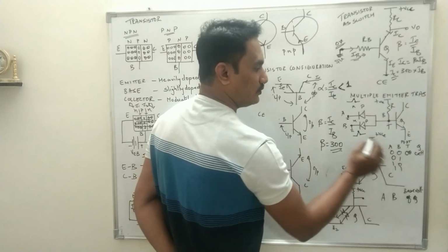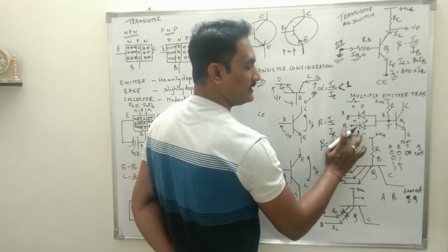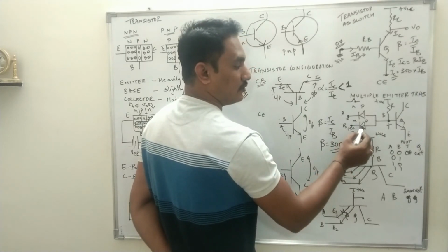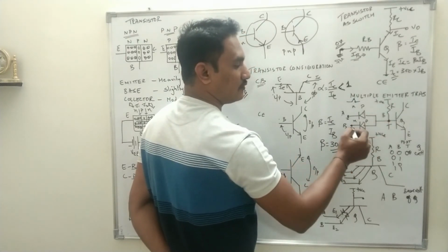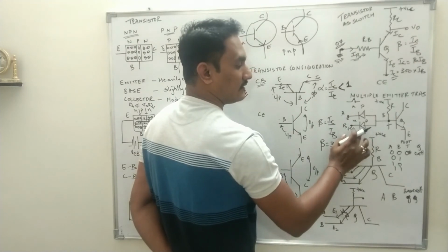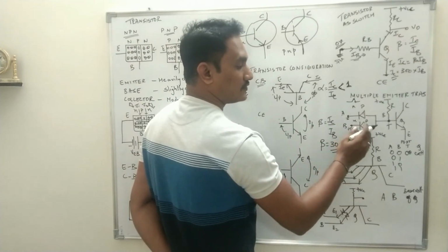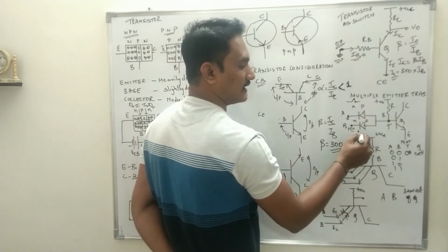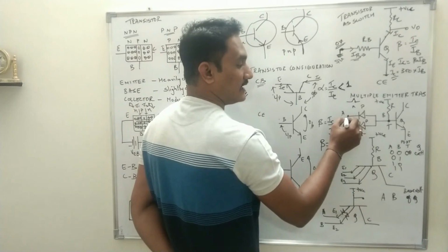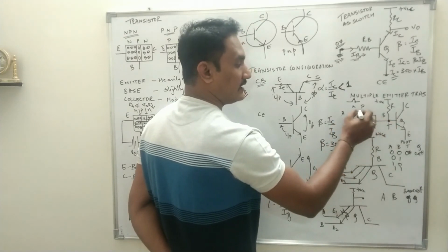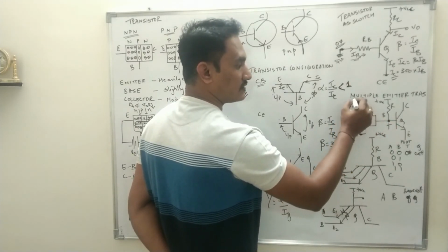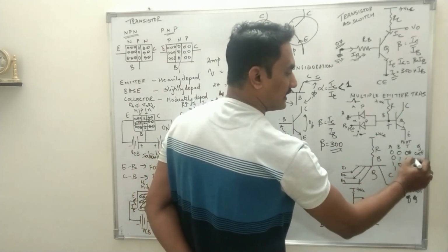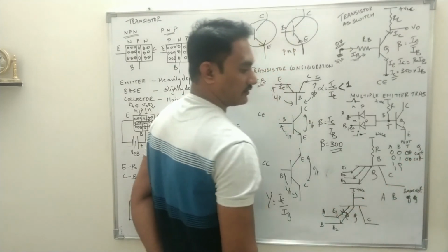Similarly, A 0, B 1, that means A is still grounded, B is plus 5 volt. Now what happens for this lower diode? Both the junctions are connected to positive terminal, so it will be acting as an off switch. No current will flow because there is no potential difference for current to flow. So we say the diode is reverse bias. But as A is grounded, T gets connected to ground through this diode because it is acting as an on switch. So potential at T still will be 0 volt. The transistor will be still in cutoff region.